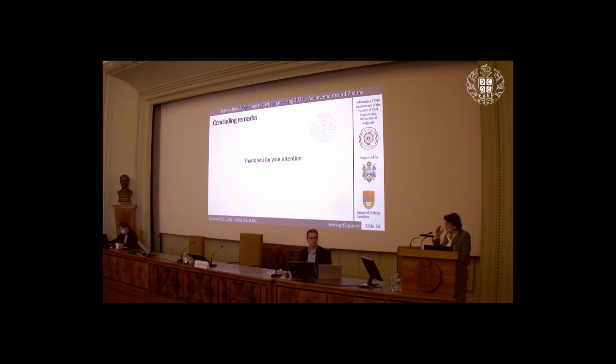But to get the profiles over the whole area of a wind farm, they just go with the CPT tests and make their decision on what ground profile there is. So I don't say that I would go one way or the other. My approach is to look at the evidence that is there and then make an engineering judgment on what to use and what not to use.